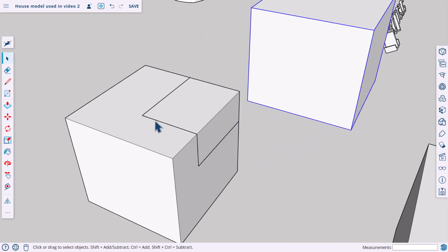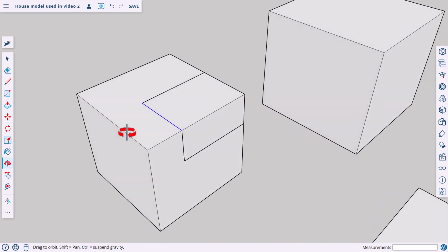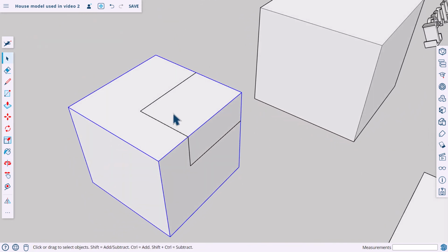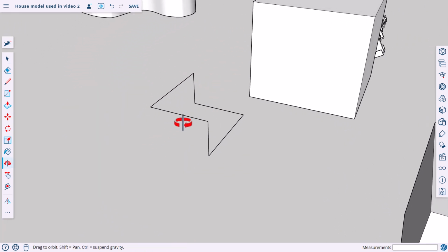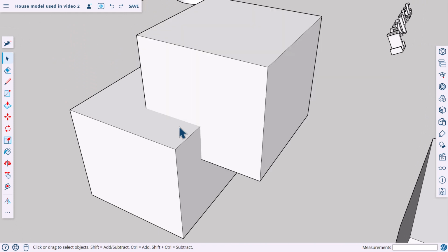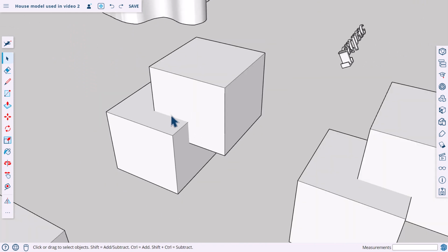And you see how it actually has created a series of lines. They are independent of this object. So the lines are totally, if I were to delete this, they're just kind of in space here. But you can see that created the intersection point between these two. This is great if you have irregular non-solid geometry. But we have solid geometry, so we can use the solids tool.